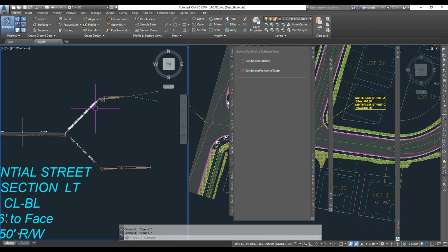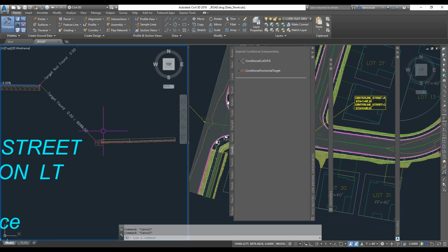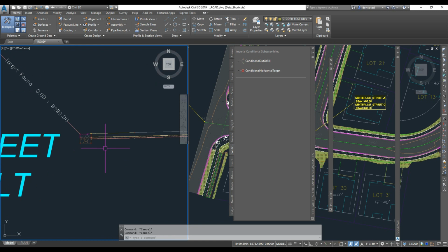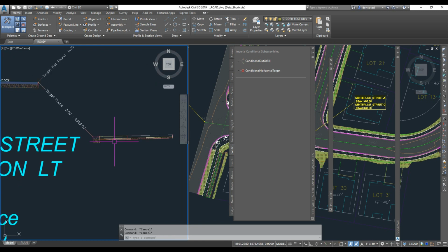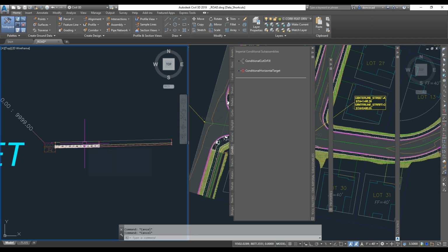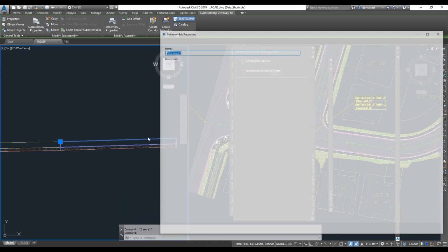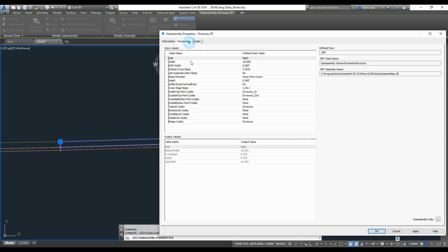This is the conditional target assembly, so if the target is not found, it's going to draw that step curb and a driveway, then it's going to go to a daylight planting strip, and if it is found, it's going to draw that flat curb, and then that little apron right there in the sub base. And like I said, I made all those out of the generic pavement structure. I just changed the link codes and everything, customized that, and it works sweet. So there's your code: daylight in, daylight out, driveway.